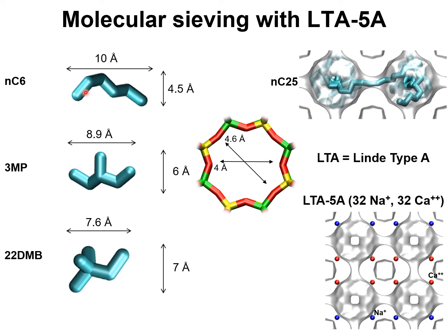It is possible for a linear molecule such as hexane to diffuse relatively easily through the 8-ring windows of LTA 4A zeolite, whereas the monobranched isomer and the di-branched isomers are limited in their ability to hop from one cage to the adjacent cage because the dimensions of the molecules prevent the intercage hopping.